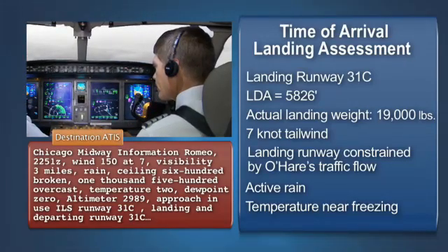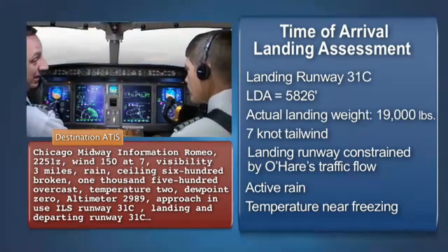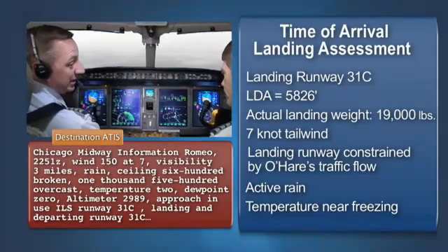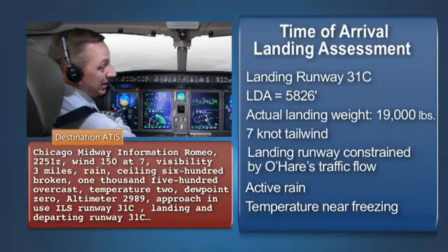Pilots should also look beyond the current conditions and plan for the worst-case conditions. Additionally, operators should use the most adverse reliable braking action report if available, or the most adverse expected conditions for the runway, or portion of the runway that will be used for landing when determining the landing performance assessment.